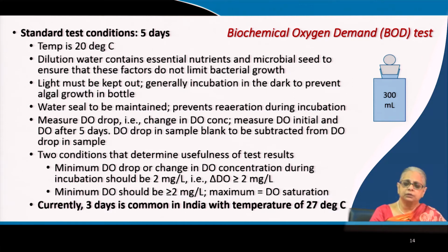So one more thing to note is that the BOD bottle is manufactured in a particular way, and the main difference between other bottles and a BOD bottle is at the top end of the bottle. So it's a cylindrical glass borosilicate bottle, and the top part of the bottle has an inverted frustum of a cone.